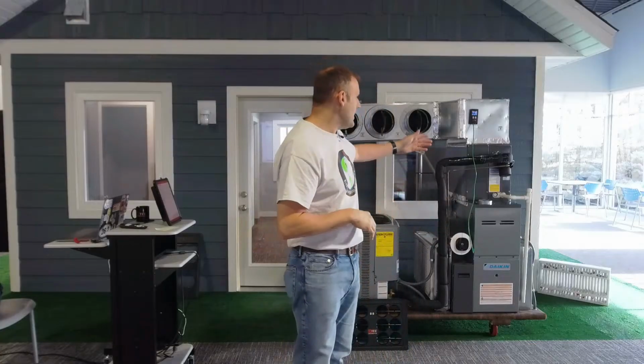That way, at the end of it, you can get a report. The report shows you not only the total pressure against the fan motor in the furnace, but it also breaks down the pressures across different components, like the filter. How bad is the supply ductwork on this install? What does the return look like? All of that is broken down with separate dials and instructions on what you can do to fix those if they're problematic. We're going to showcase that here in a minute.